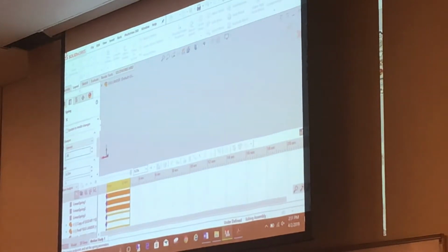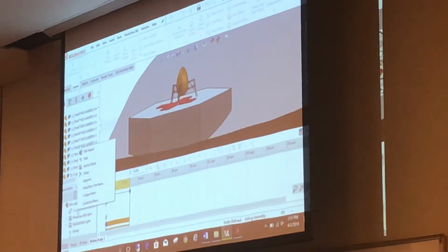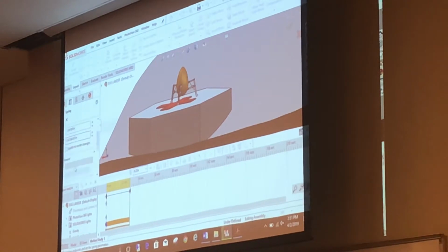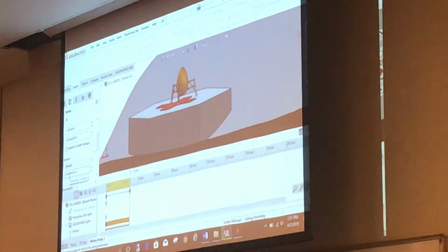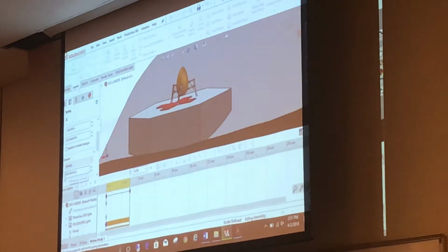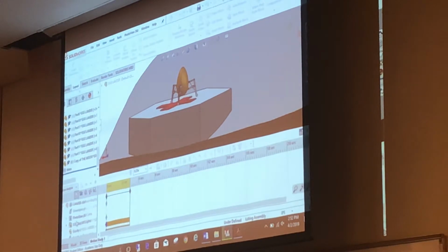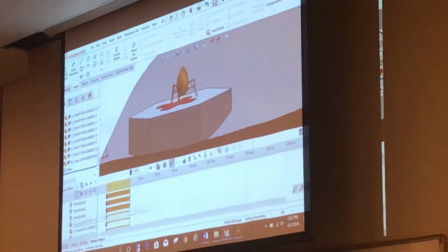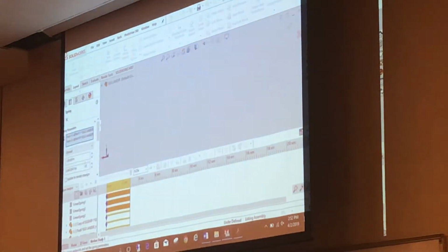So, I'm going to put in a value of 0.05 for our damping, and I'm going to do that same thing to each of the other springs. And by the way, if you just type in a value and hit enter, the units on your damping constant can also remind you of this idea, because if you look at the units of your damping constant, it's pounds force per inches per second. So it's a force per unit of velocity. Okay, so there's spring 2, and do the same thing on spring 3.